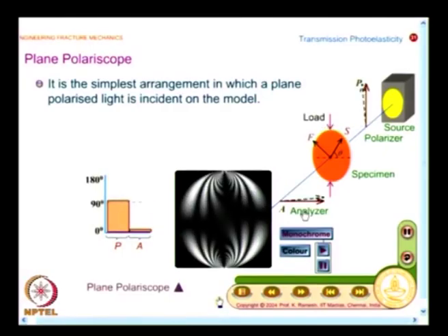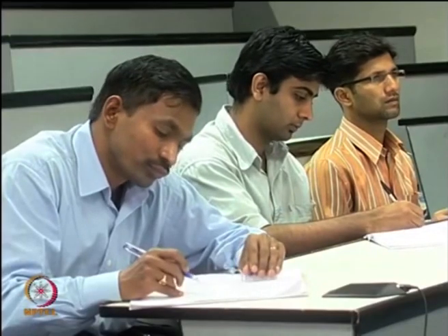For a plane polariscope, trigonometric resolution is also needed, because that gives you an understanding of what happens in each optical element. We did the logical explanation, we did a trigonometric resolution, we will also analyze the plane polariscope by Jones calculus. The reason is, you understand all the three methodologies. A logical explanation may not be possible when I have many optical elements. Many optical elements will complicate your logical explanation. So, we will see what happens in a plane polariscope.